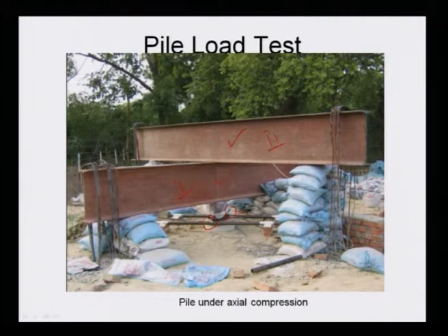This first girder has been connected by means of reinforcing bars of the anchor pile. If you look, this is my anchor pile. Whatever bars there are, these are the main longitudinal bars of the anchor pile. These main bars of the anchor pile have been tied to girder 1, and at the opposite end also tied with girder 2. Once one girder has been placed on the pile head, there will be a gap from the ground, so it may fall.